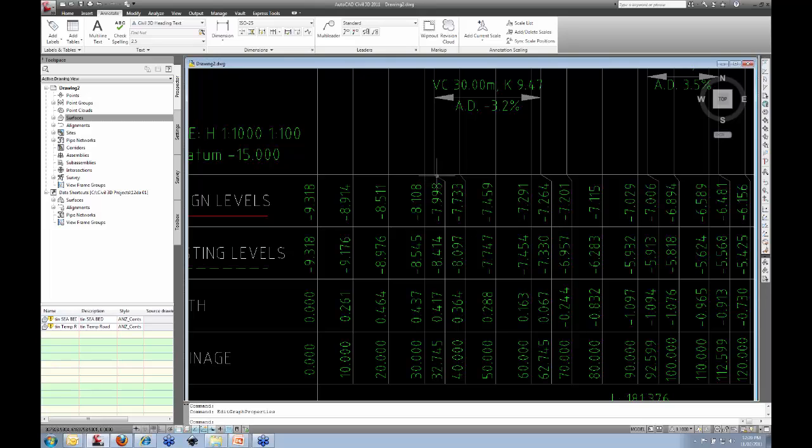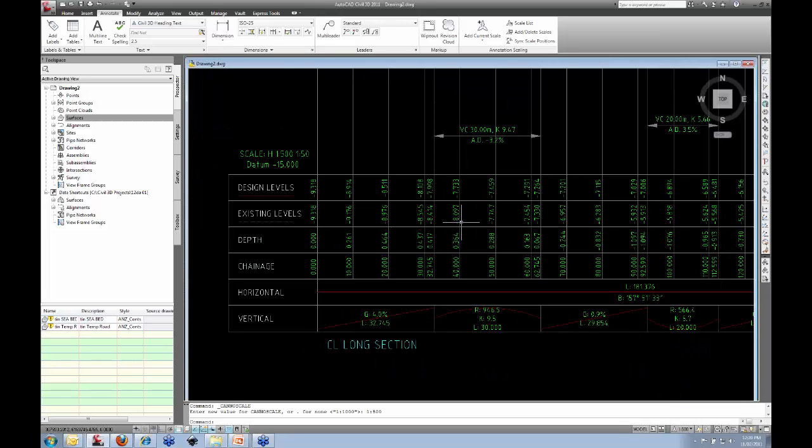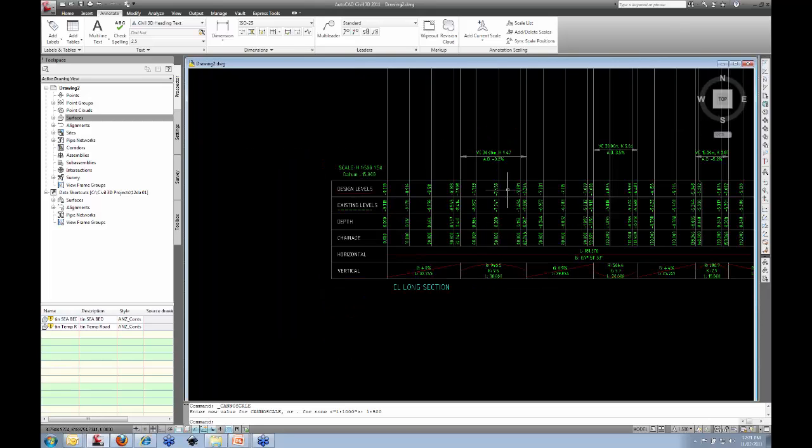Now this business of staggering the vertical lines coming down to label everything, that wasn't in the software in the past because it's not done in the US. It took a long time to come in, but when they finally got it in, it's done a good job, because if you change your scale to 1:500, for example, the staggering isn't necessary, so it doesn't happen. So as you produce this drawing at different scales, you're not restricted to having staggers on the whole time. It's quite intelligent in terms of dynamically changing for these things.